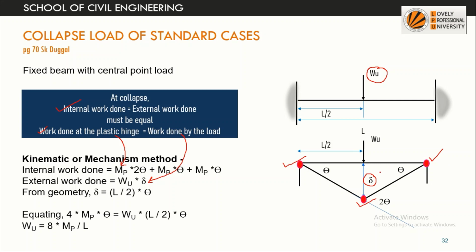So now we'll calculate the internal work done. Moment into rotation, so Mp into theta. For the first hinge it will be Mp into theta.